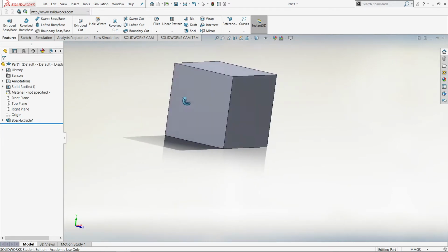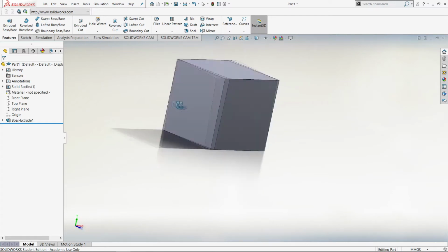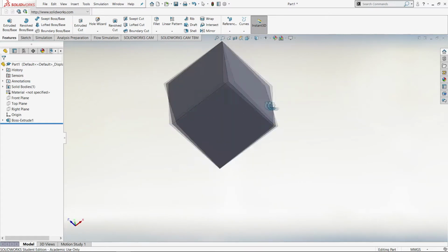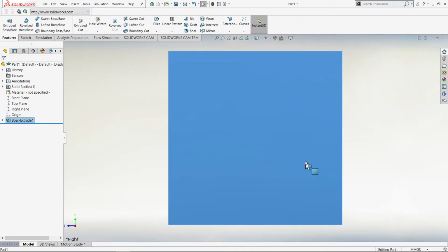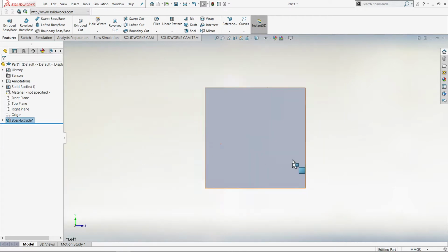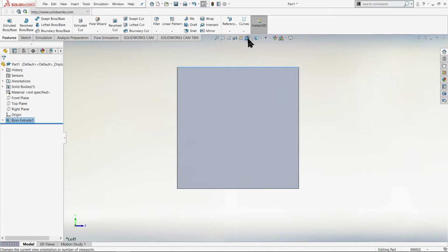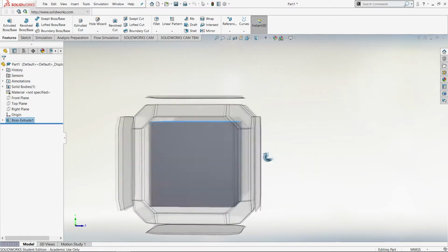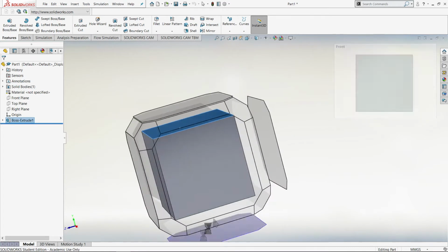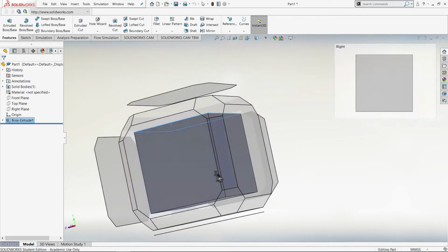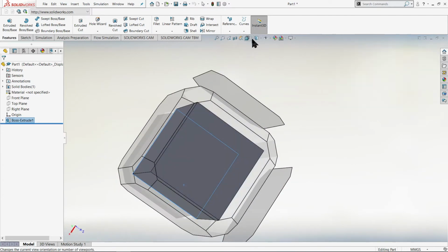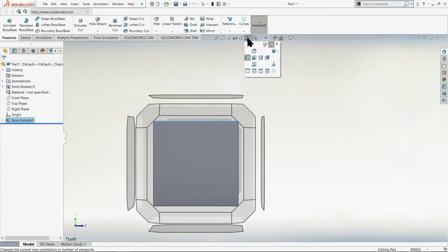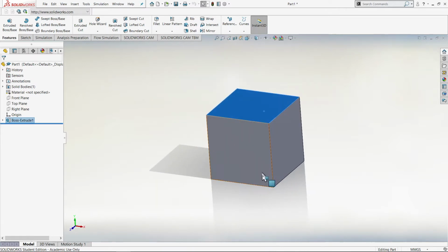As you can see, you can push in your scroll wheel on your mouse to rotate the view. You could also change the views by holding the right click on your mouse and dragging up, to the right, to the left and down, or you could simply click on the top where it says view orientation. You can choose your view here. So let's go ahead and choose the front view. We could always just click on the little arrow to the side of the view orientation, and then you can go ahead and click on the front view. A bit simpler doing it that way sometimes.